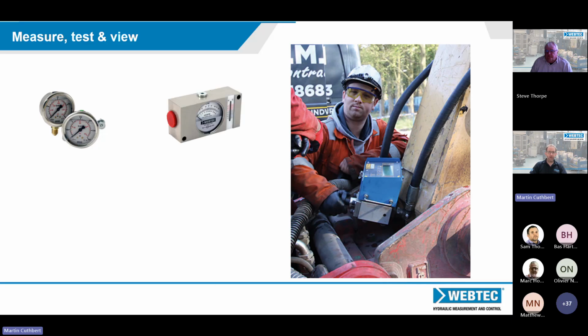If you're also monitoring the flow on a system, there's an example of WebTech's flow indicator. It's just an all mechanical flow indicator. They come in different shapes and sizes. That one also shows temperature. You could screw a pressure gauge into the top of it and get flow, pressure and temperature. A great, reliable visual indicator of what's happening on your circuit.